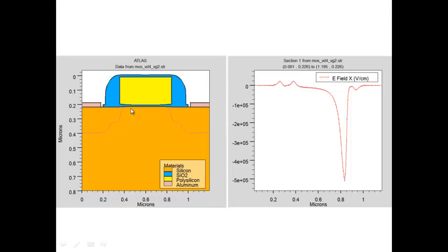What happens is, in this high field region, whatever electrons are injected from the source reach this particular point here. The moment they reach this point, they are swept by the very high electric field into the drain. Whatever electrons reach, the high electric field just pulls all those electrons into the drain, and they get collected. So although it's a high field region here, this is not the one which controls current. Whatever number of electrons reach this high field region, they immediately get collected.